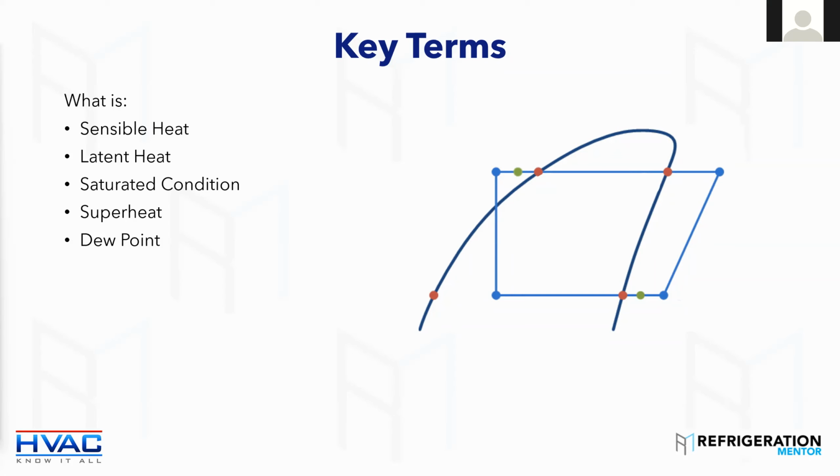Work on a building. They got some in-floor cooling actually down in Halifax, and there's alarms on it, so you've got to keep the temperature of that above 2 degrees above the dew point, or you're going to have some slippery floors. Yeah. So the dew point is, let's see, high dew point equals less evaporatability. Yeah, that's a good way to look at it.